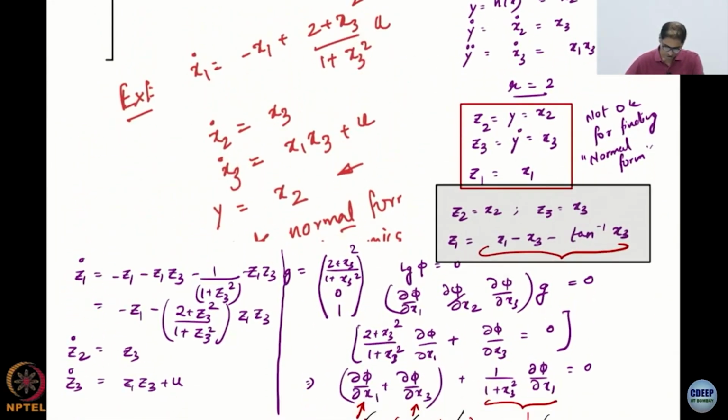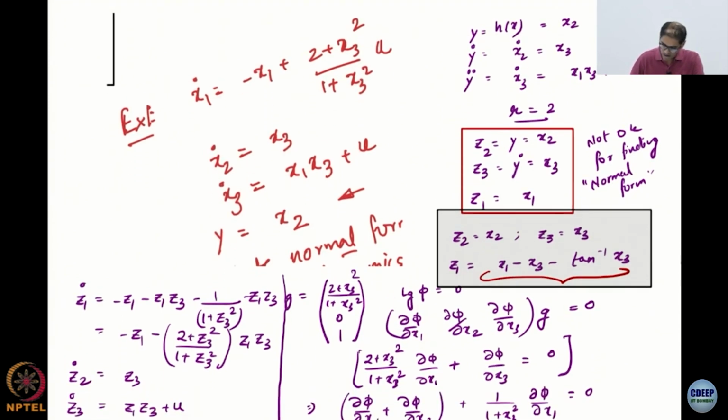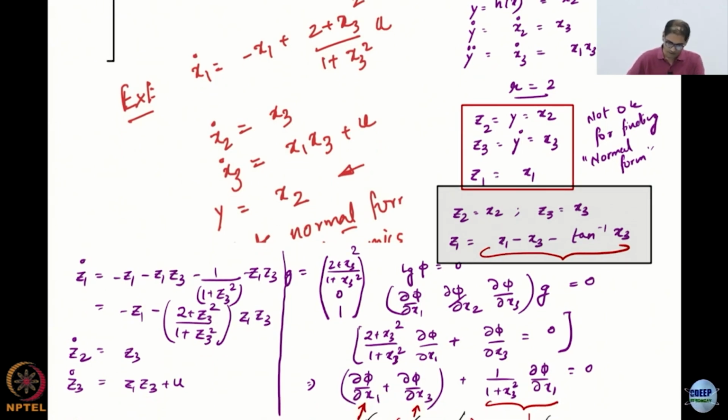We also sort of, anyway, did this example on feedback linearization, this system. And anyway, this is again going back to the previous material. We just took an output which was given to us, and then computed the relative degree of the system. After computing the relative degree of the system, we saw that it was 2 and the state space was 3 dimensional. So, obviously, I need one more additional coordinate,